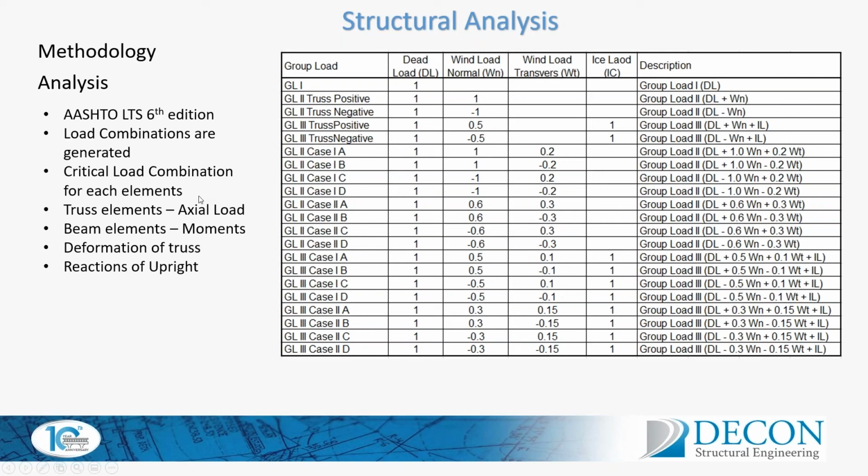Once we get the load combinations, we came to a conclusion for which is the critical load combination for each element profile, and we checked for axial load, whether it's tension or compression for each truss element, and for the beam element we checked the moment capacity.